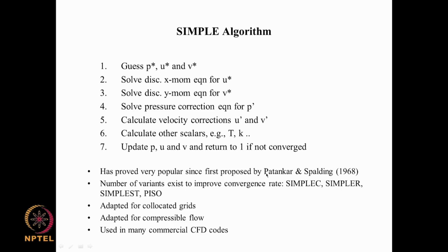So this has proved to be very popular since it was introduced in 1968 by Patankar and Spalding and a number of co-workers. A number of variants and improvements have been made to this, and you have SIMPLEC, SIMPLER, SIMPLEST, PISO, and all these methods are variations or inspirations of this method.